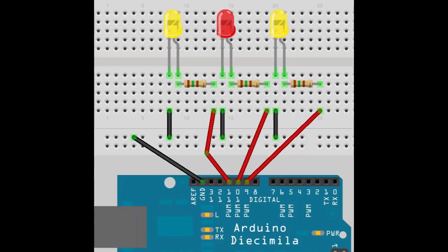Now, note here that these sockets are connected to one another not horizontally, but vertically, or across the breadboard. Also note that the gray line in the middle denotes where there is a channel down the middle of the breadboard, and the work areas below that channel are not connected to the work areas above that channel. So you can't set up circuits across that channel unless you use a jumper to connect them together. That's why all of the work on this particular diagram is below that gray line, or on one side of the channel. Now that we understand that, let's work our way through the circuit.